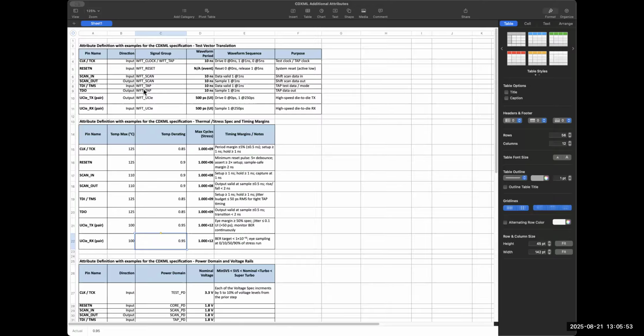If it has to apply the inputs, it needs to also know, relative to the clock period, what is the relative period, and also for the strobe window. The strobe window will be adjusted for the ATE for the pin margin. ATE engineers will do some more fine tuning and adjust the timings needed for the arrival and for the strobe and the input forcing type of applications. So those pieces of information are the placeholder. I have given specific examples for each of the cases.